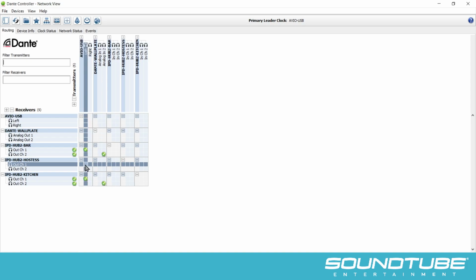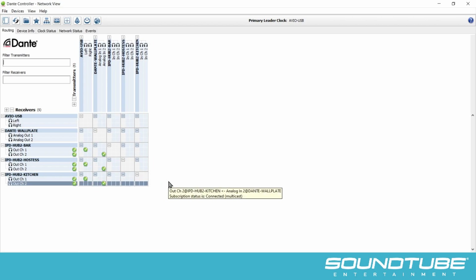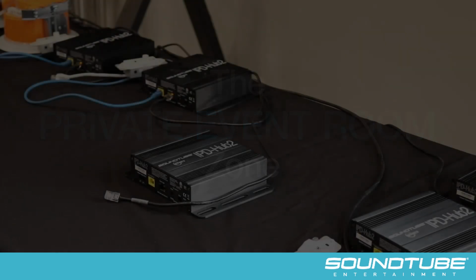Back in the Dante Controller software, we will establish our audio paths. Again, we are sending audio from the Avio USB device or laptop to the IPD-Hub 2's output channel 1. We are sending Dante wall plate audio via the paging audio to output channel 2. We're now ready to set up the private event room.